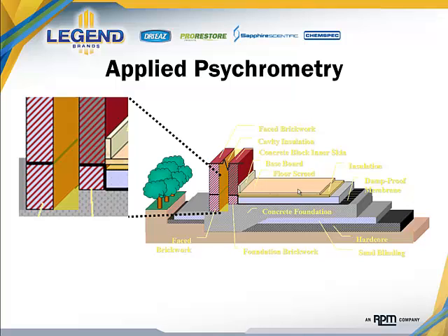The amount of air movement can be evaluated using a hygrometer. Simply placing a hygrometer on the surface of the wet material will verify that we have enough air moving across that surface. Substantially higher humidities at that surface mean you don't have enough. Add more. Just this one adjustment in and of itself will have a dramatic impact on your overall drying times. However, we have to think a bit more forensically and look deeper into the structure and look at some of the other surfaces that may be at play.